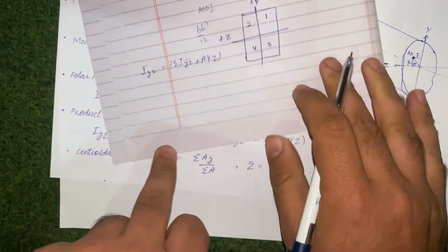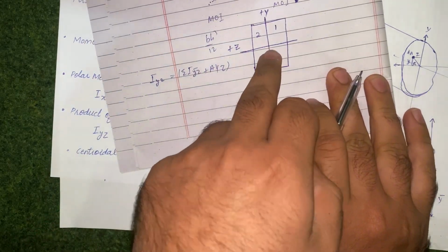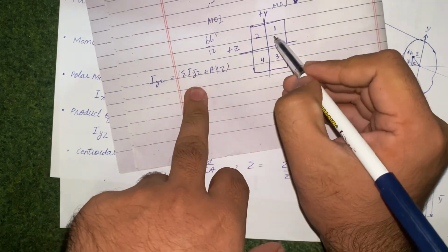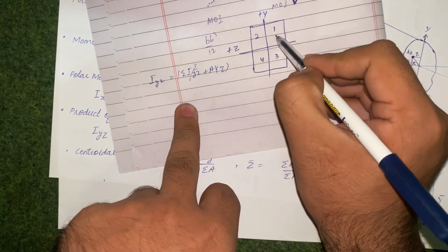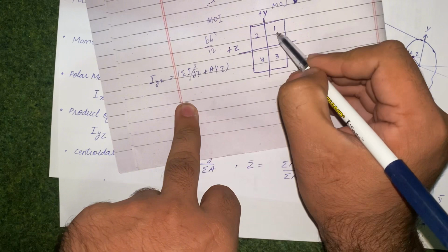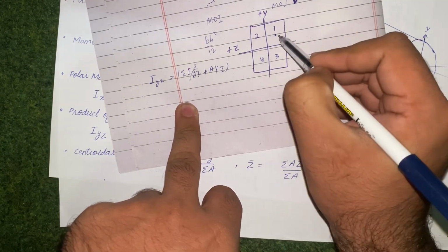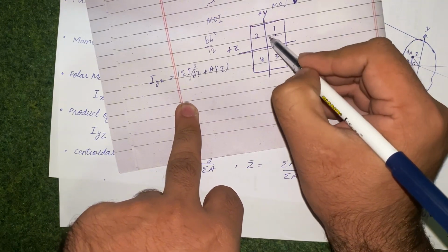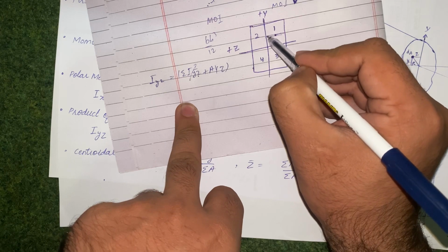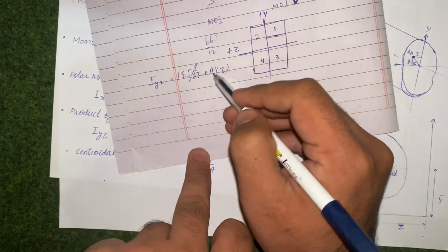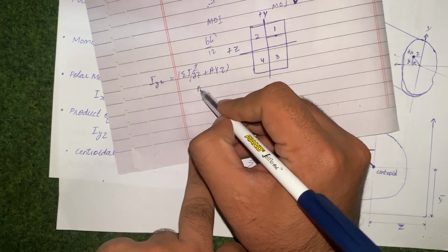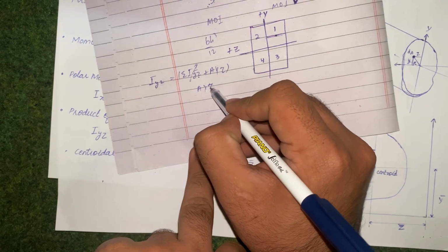So this is for one section. We know that the product of inertia terms for a symmetric object will be zero, because the product of inertia of the individual section here will be zero. In this case, its principal axis will be this, and on the principal axis the product of inertia is zero, and we are left with A, y and z.